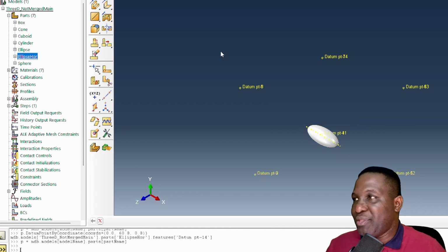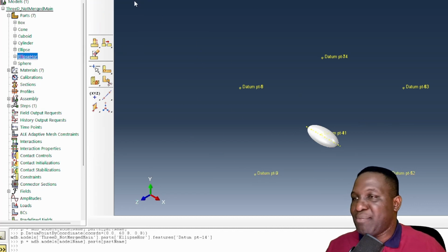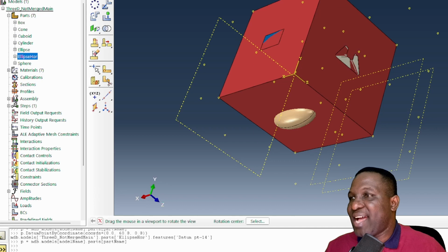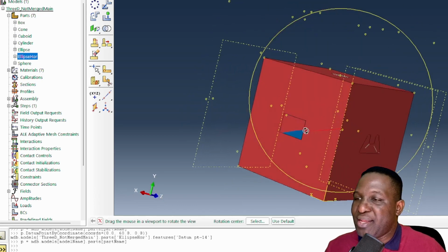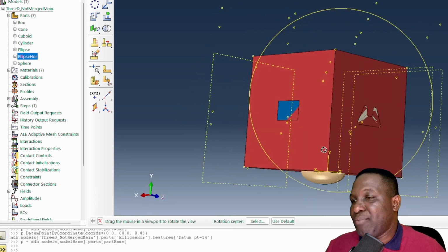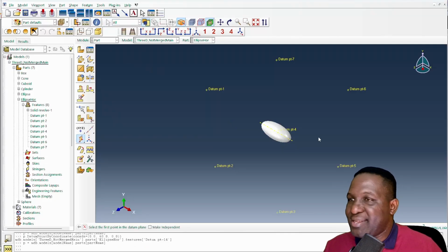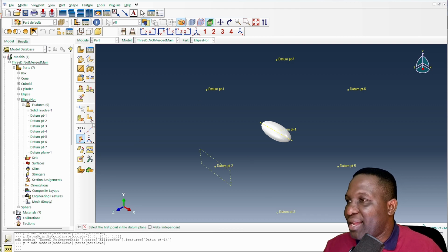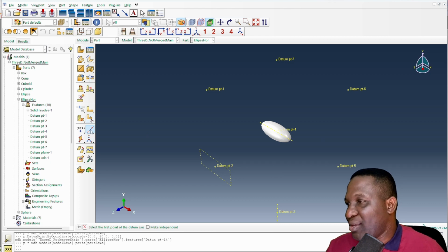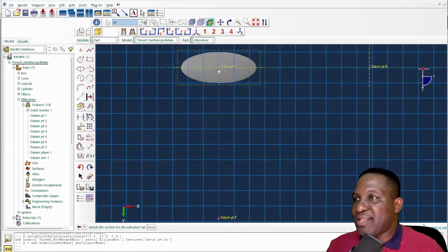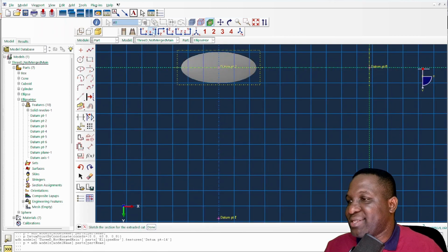Now, if you study the system again, if you go back to the assembly module, how best are we going to trim the horizontal ellipse? Okay, the YX plane that we used before will also work again. So we create this, that, and that to create the plane, and then with the vertical axis, we use that and that to create the vertical axis. And then we can go ahead and just extrude-cut. So we use this option, and we use this option again. All right, but we want it to be in the correct YX axis.